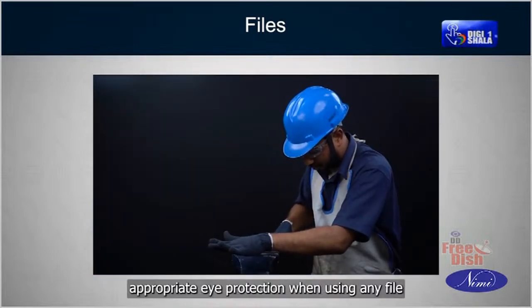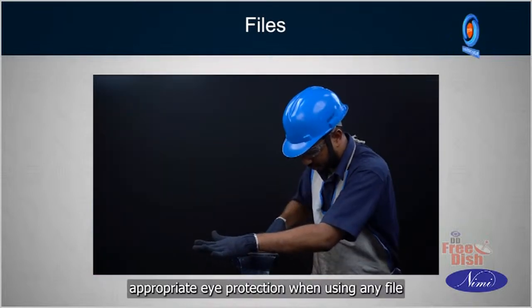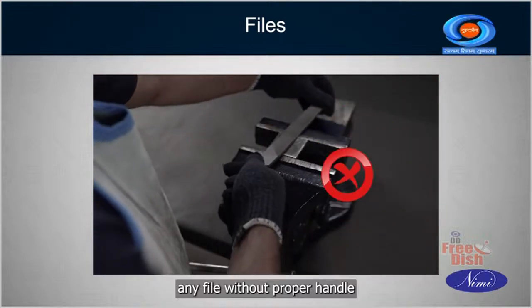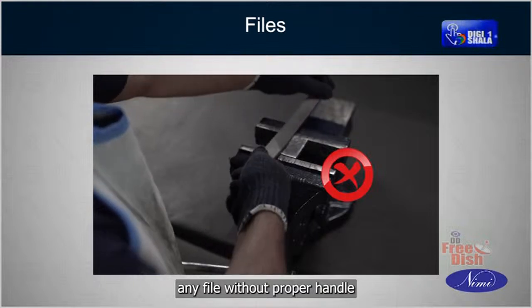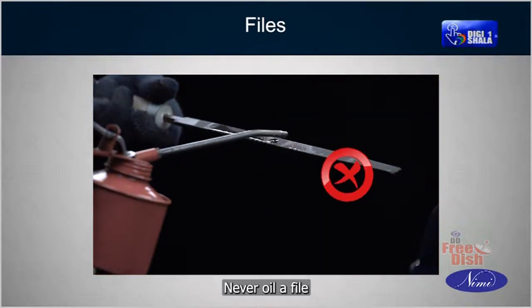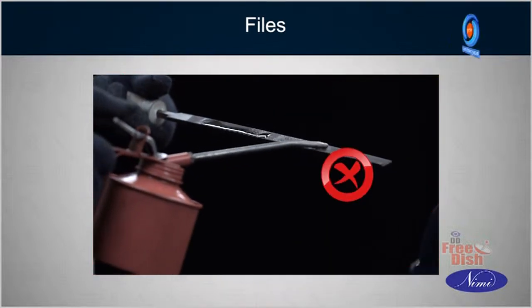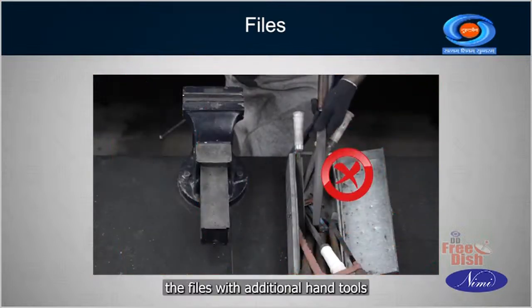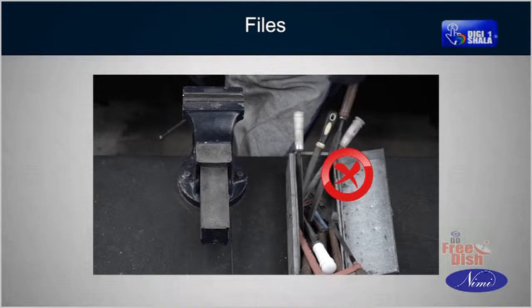Always wear appropriate eye protection when using any file. Never use any file without proper handle. Never oil a file. Do not place the files with additional hand tools.